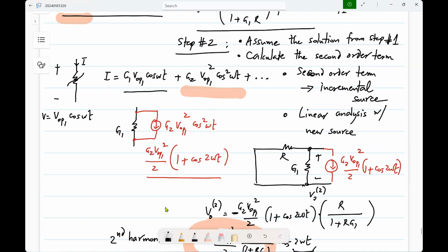Yeah, in a MOS transistor, for the classic long channel MOS transistor, you can derive it from physics, but you can measure the voltages and currents, right? And from that you can get it. For resistors and so on, all of them will have some nonlinearity. So you make measurements over some range that you think is reasonable, and then you get the nonlinearity.